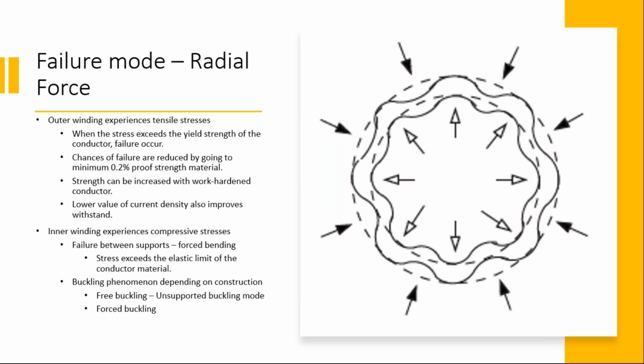In order for us to do one thing better, we have to compromise the other. So from there, we want to go for a thinner conductor, but it's work hardened, as the conductor is manufactured by our vendors, and we give a proof strength of so many psi. They manufacture that, so we gain strength within the copper itself.